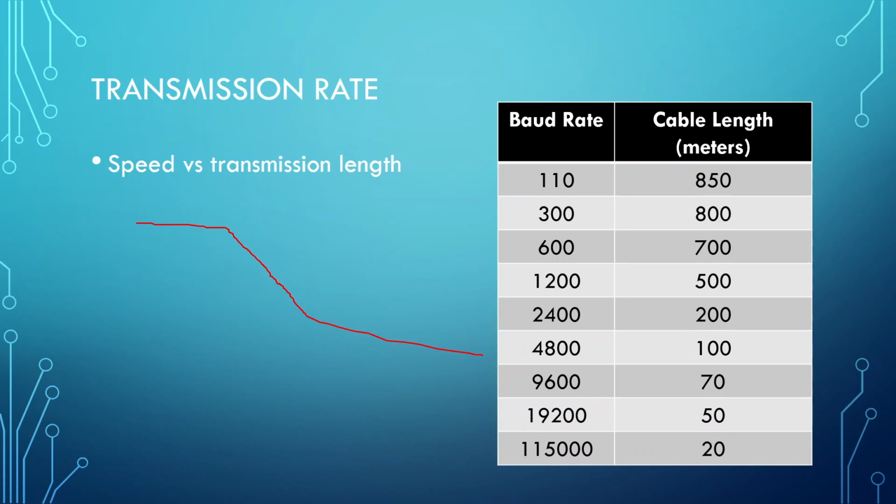So the longer your wire, with these two wires right next to each other because there are two of them in that cable, the bigger that capacitor becomes. And capacitors store energy. So if one moment I'm telling you here's 25 volts, and the next moment here's negative 25 volts, it's like, hold on, I have to drain my voltage down. Let me dump the pitcher out. The longer the wire is, the smaller the hole you're dumping that water in. So it takes time to uncharge and recharge that capacitor in another direction. That's why the length of the wire matters. By keeping the wire shorter, we have a smaller capacitance, which means we can transition faster.